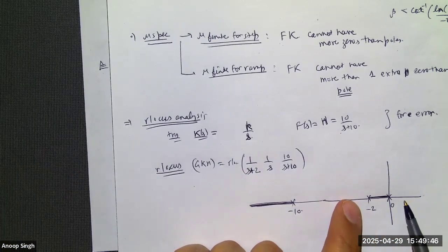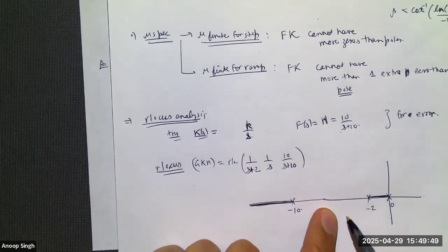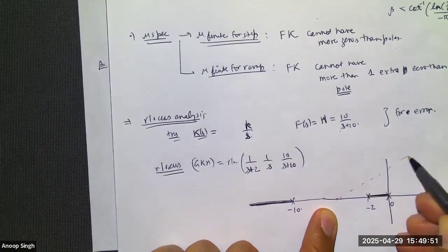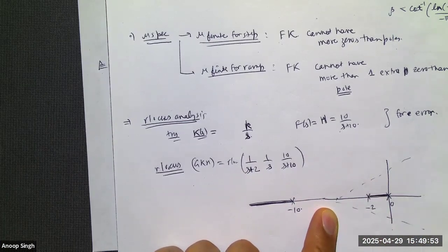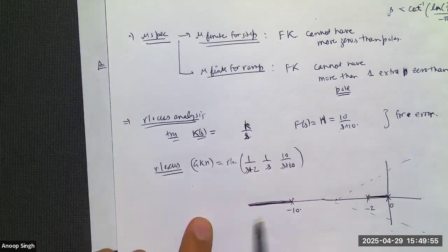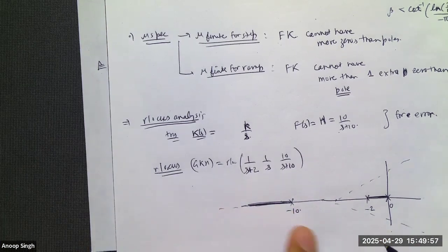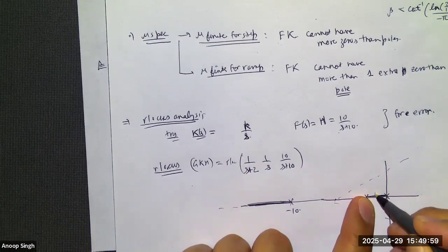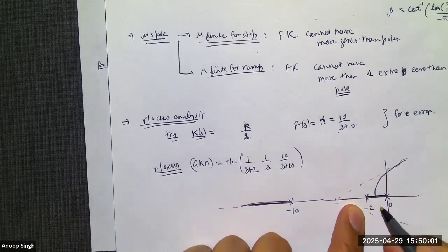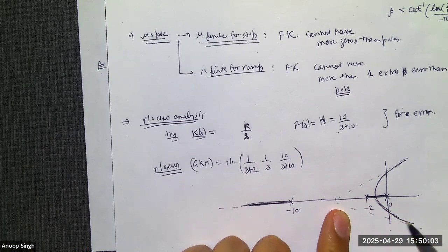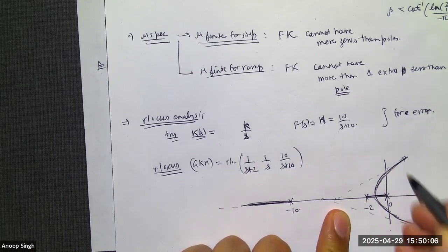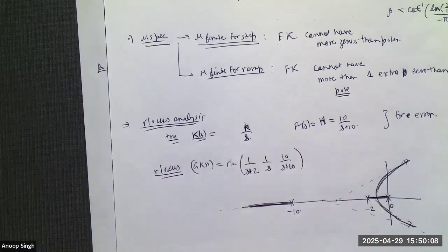The center of the asymptotes is the average of the 3 poles, somewhere over here. This pole is already following its asymptote, great for it. And these 2 poles will come together, touch briefly, and then move along their asymptotes. So that's the idea. So what is this root locus telling me?